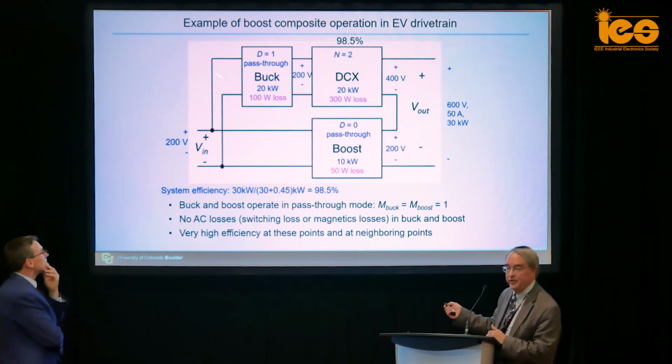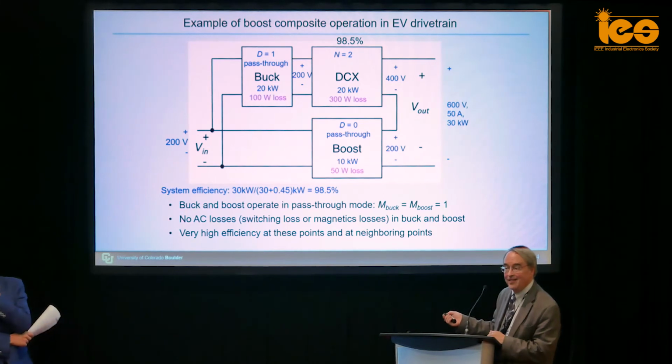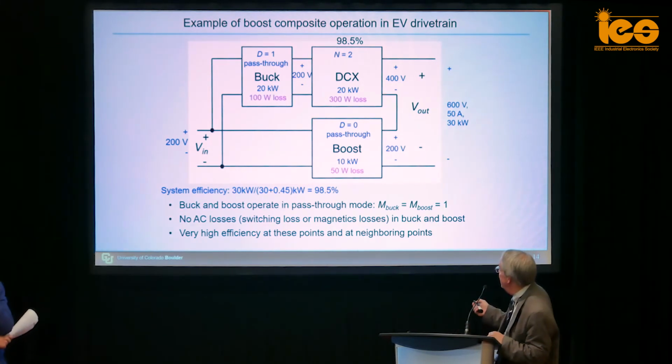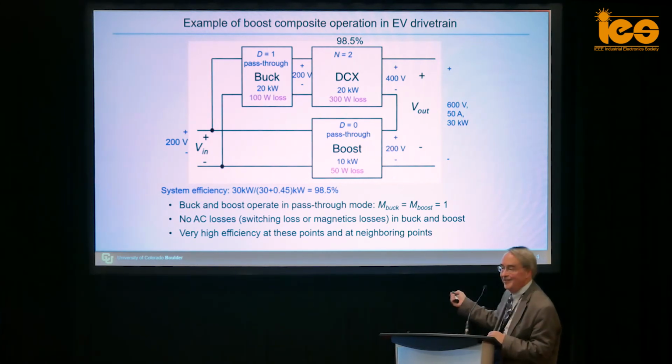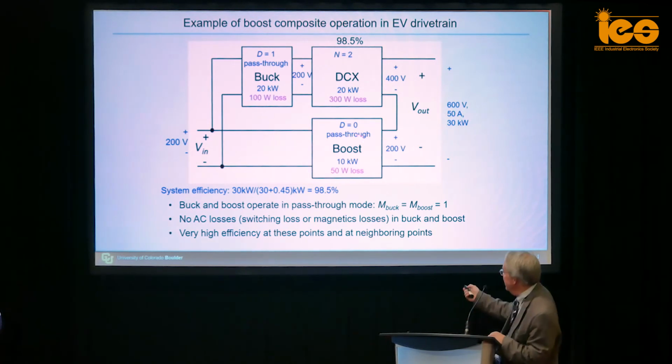This is just one. The boost is really working as a pre-regulator, as a regulator, adjusting the 200 volts. It depends on the output voltage, if the level is high or not, basically. Right, so if we want more than 600, we start raising it here, and we increase the duty cycle.